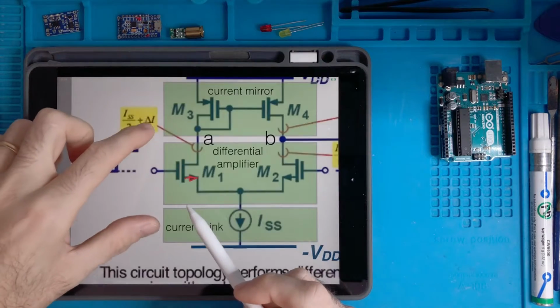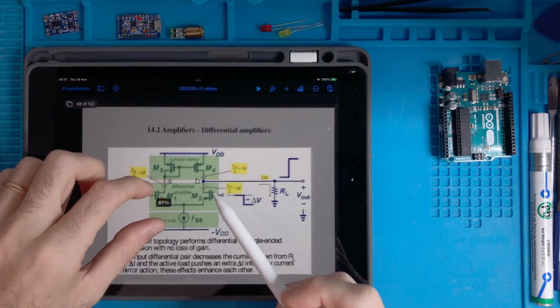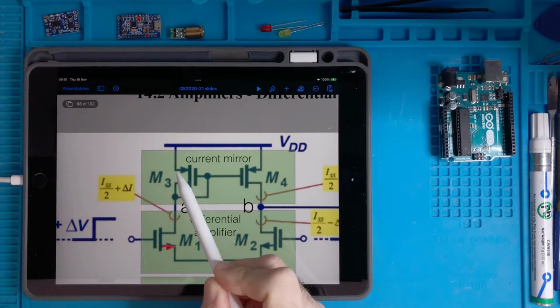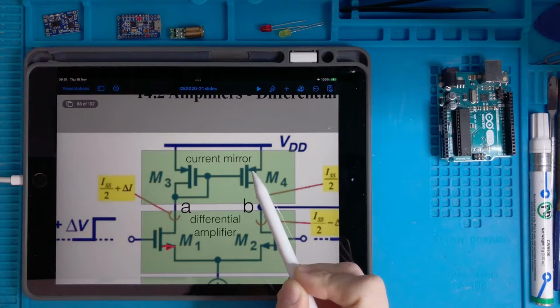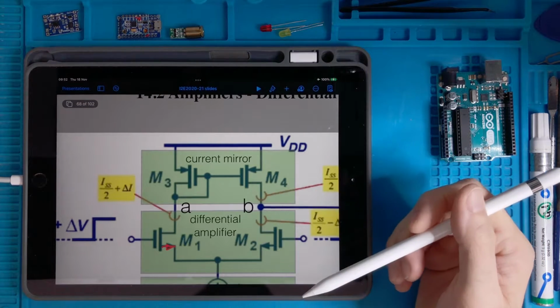So here we have an N-type MOSFET, while here we have, with this other symbol with the arrow pointing inwards, a P-type MOSFET. So we don't need to repeat everything for the P-type transistor. It's exactly as the N-type, but the only thing that changes is the direction of the current with respect to the VDS voltage.